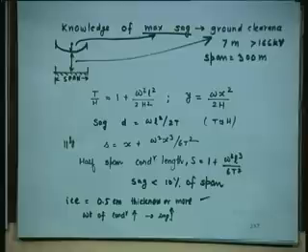How much ice can there be? 0.5 centimeter thickness or more. Then we say there is ice, and you should consider that ice. What happens because ice forms around the conductor? The weight will go up. Weight will go up, sag will go up, because sag is precisely because of weight. If the conductors were weightless, there would not have been any sag.